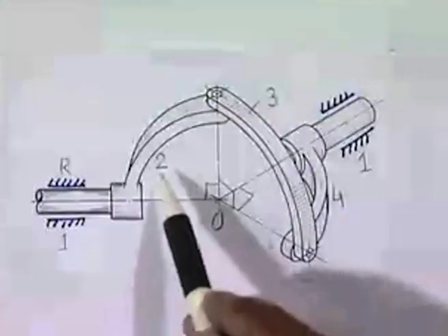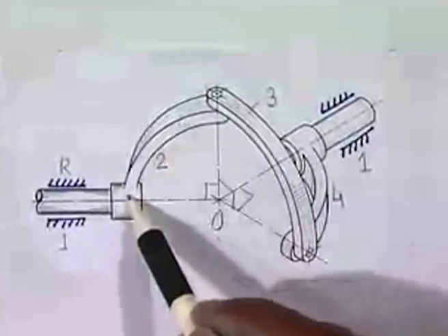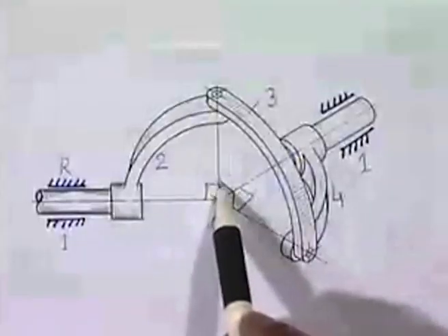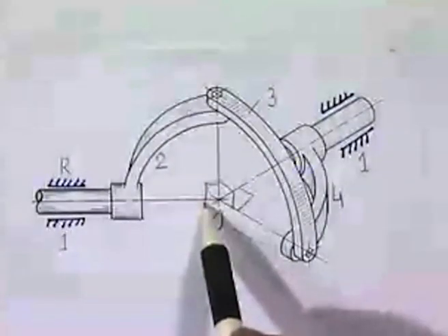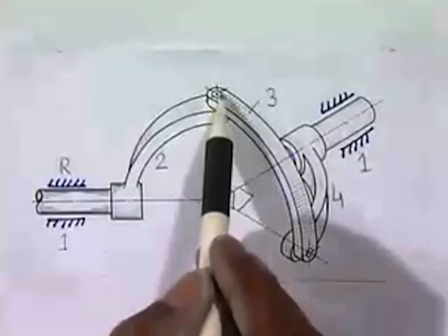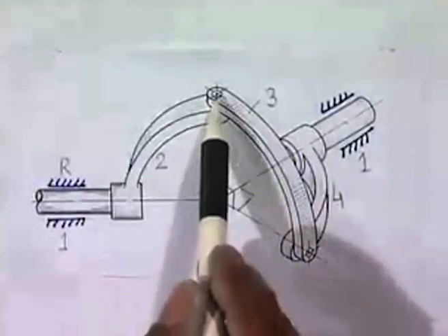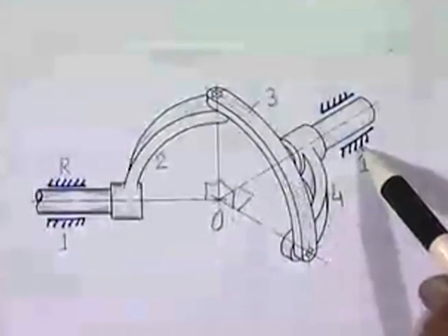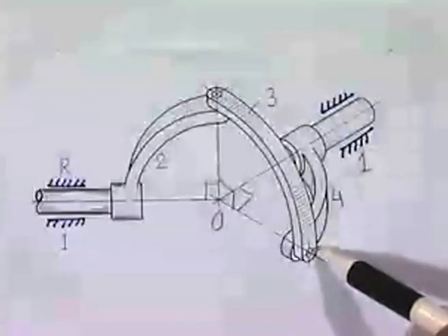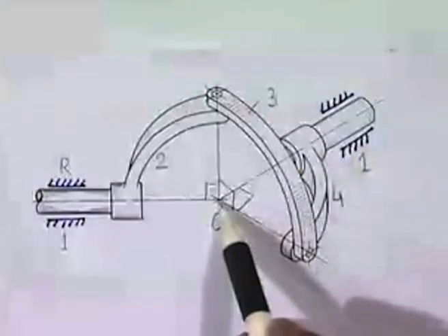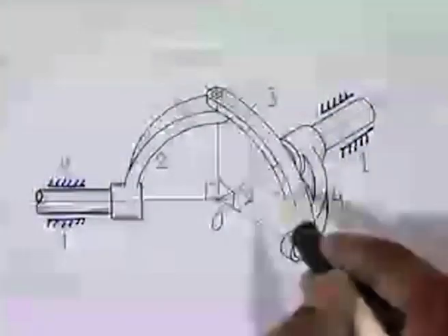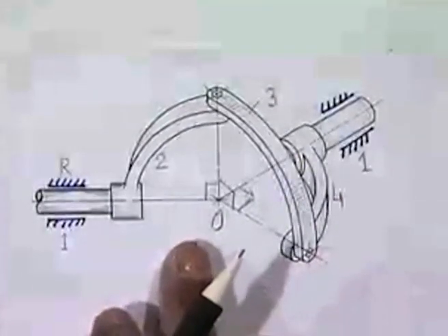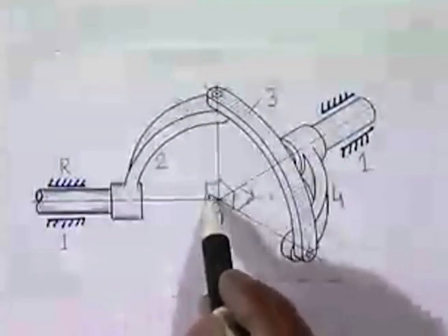If we consider the two revolute pairs belonging to the same link, link number 2 has these two revolute pairs here and there, and the angle between the axes of these two revolute pairs is 90 degrees. Link number 3 has two revolute pairs, one here and one there, and the angle between the axes of these two revolute pairs is also 90 degrees. Link number 4 has these two revolute pairs, one here and one there, and the angle between the axes of these two revolute pairs is also 90 degrees. So, this Hooke's joint is a special case of a spherical mechanism or spherical linkage where all these angles are